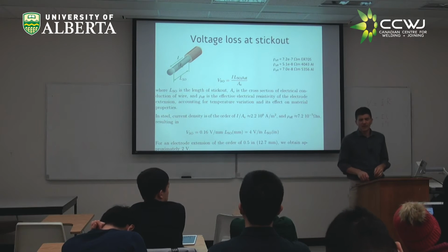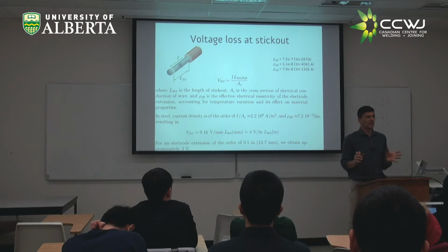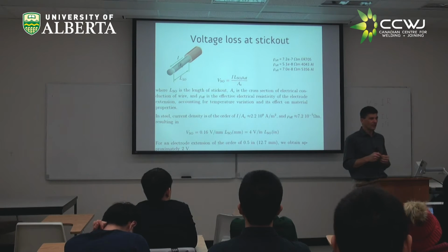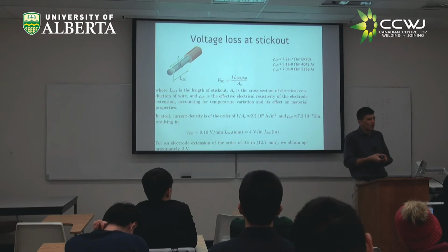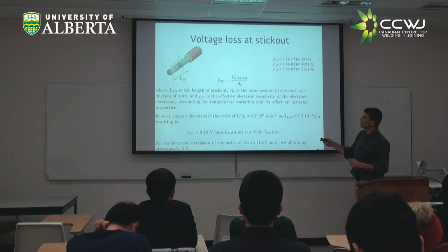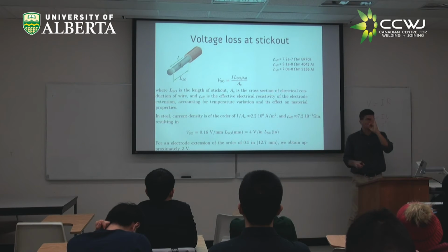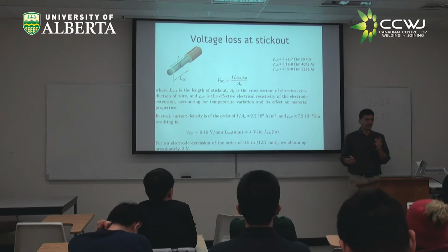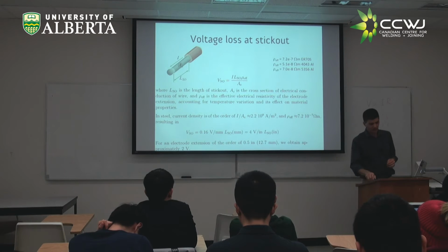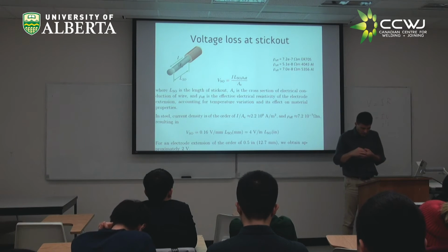Now, if I have flux core of the same diameter, is that the same cross-sectional area for resistivity? No, it's smaller, right? Because now we don't have the core. It just goes around, right? So this voltage depends on the current carrying part. Same with metal core. Although the metallic powders are conductive, they don't really count, right? Because it's powder, full of contact resistance. So what we look for is the cross-sectional area of the metallic sheet.